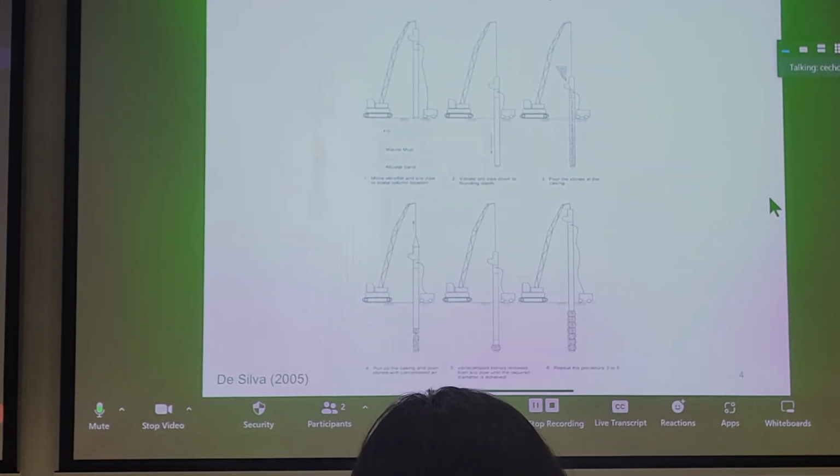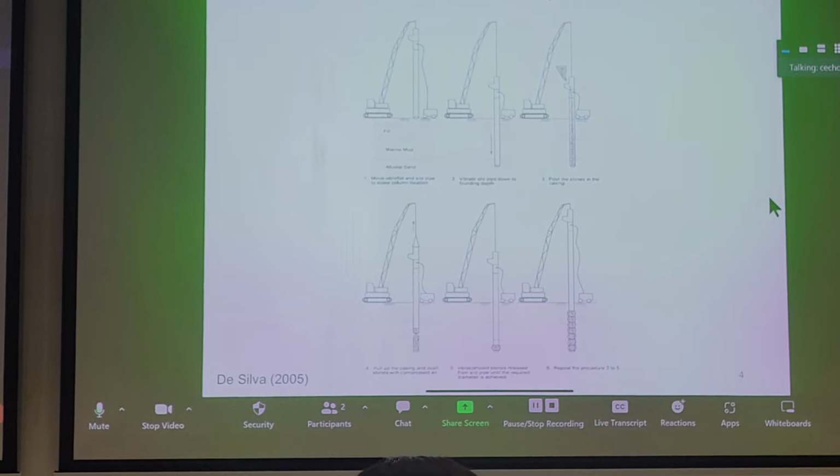Did they need to pressurize the gravel with air pressure during dry feeding to push the gravel down? Could we compact the gravel so that we displace it properly into columns? Were the columns coherent? Could we form the target column height? So they did some trials, and they decided eventually on a particular type of amplitude to use for the vibro system, and also the method: how long do you vibrate before you lift up, go back down, compact, lift up, and so forth. So essentially, the dry bottom feeding deep replacement method was used for the stone columns.